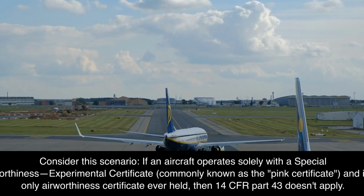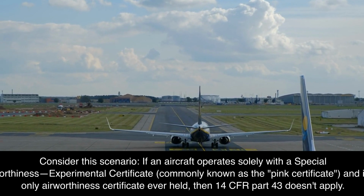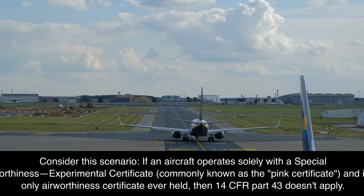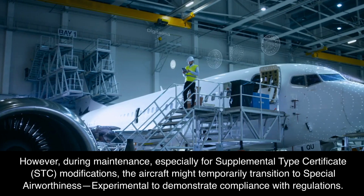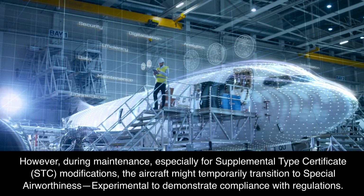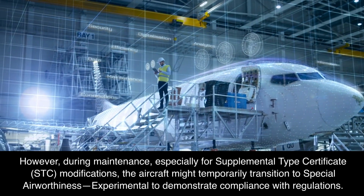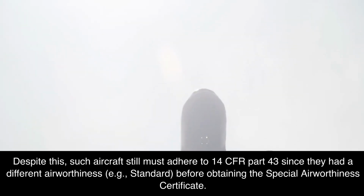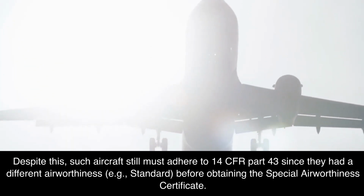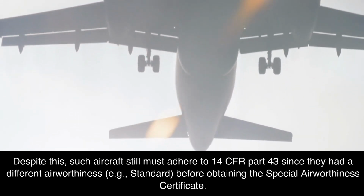Consider this scenario. If an aircraft operates solely with a special airworthiness experimental certificate, commonly known as the Pink certificate, and is the only airworthiness certificate ever held, then 14 CFR Part 43 doesn't apply. However, during maintenance, especially for supplemental type certificate (STC) modifications, the aircraft might temporarily transition to special airworthiness experimental to demonstrate compliance with regulations. Despite this, such aircraft still must adhere to 14 CFR Part 43 since they had a different airworthiness, e.g., standard, before obtaining the special airworthiness certificate.